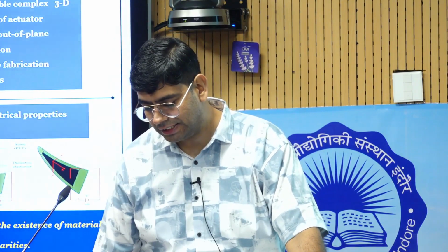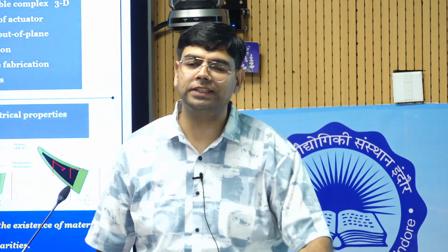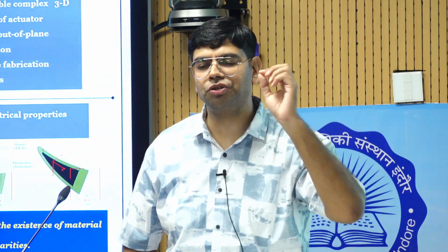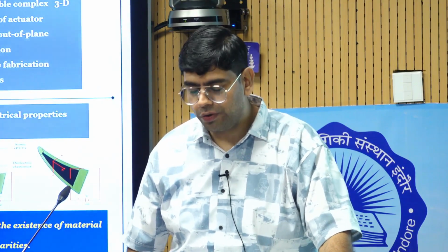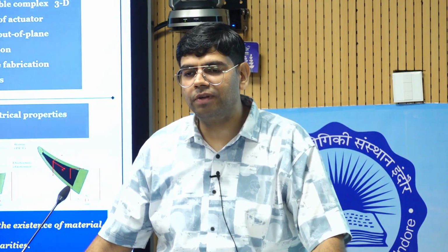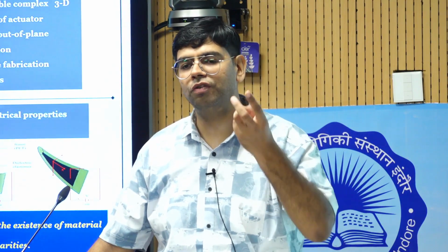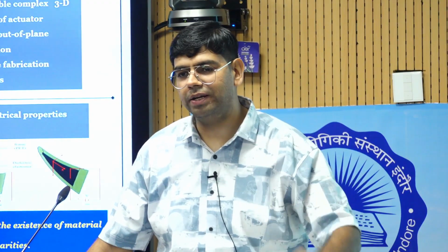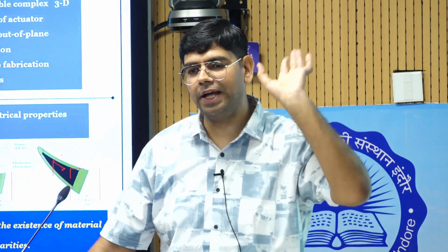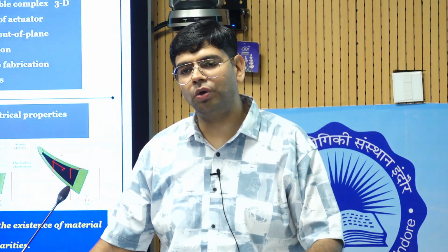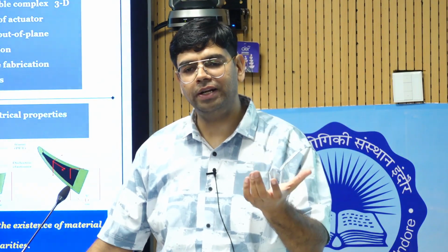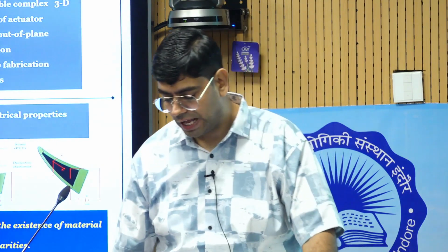So what are those challenges? This membrane already exhibits material nonlinearity. We have seen that: hyperelastic, viscoelastic behavior. Already exhibiting a strong material nonlinearity. Now what we are doing, we are attaching a frame with that also. Because of the attachment of that frame, now we are having the configuration as a combination of two parts, frame and the membrane. We will have geometrical nonlinearity also creeping in. So initially you are tackling the material nonlinearity. Now you also have to deal with the geometrical nonlinearity that arises because of the coupling of the frame and the membrane. So that is the most important challenge.